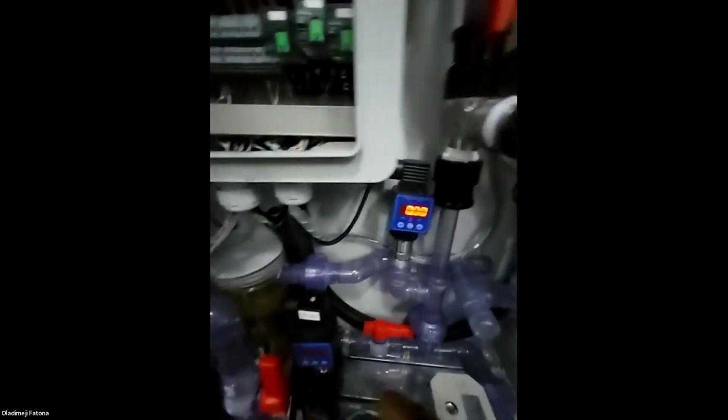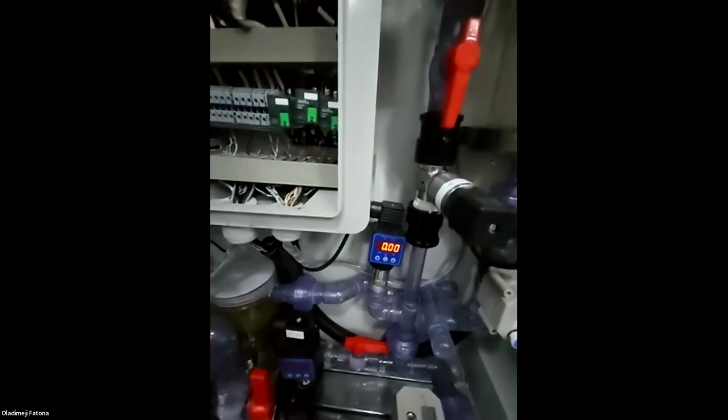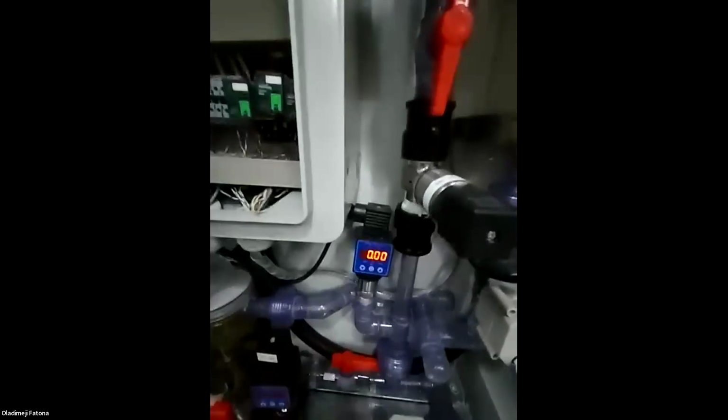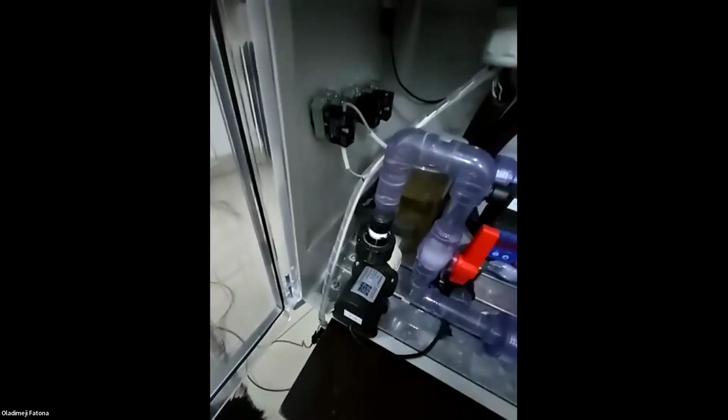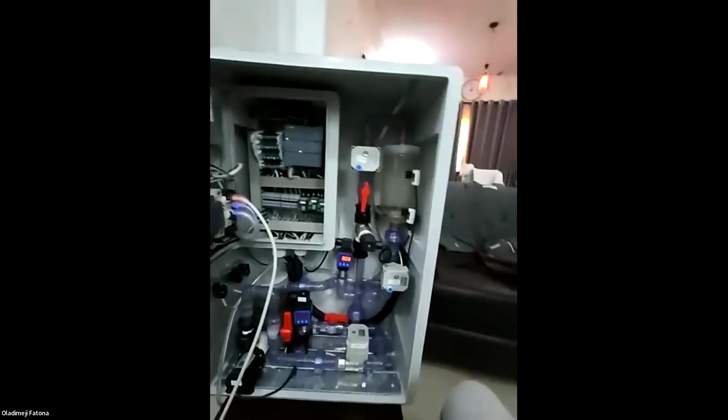Then here I have pressure transmitters. These are meant to read the pressure on the line. Right now the pressure is 0 because I would have loved to test the whole thing, but let's just manage what we have. Then this here is to record the flow on the line, the flow transmitter. Here we have a makeshift pump. It's just a miniature pump, meant to pump water in. It is a digital output. It gets the digital output from the PLC, and then it runs at constant speed to pump water through the system. So this is a simple control system that we have.